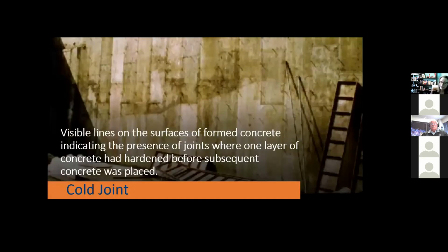But speaking of aesthetics, another thing that can happen is cold joints in concrete. You can get at times when placing more than one truck, joints that form due to one section of concrete hardening before the other is placed. Now, I don't think you can see my mouse, but you can see lines that are vertical, and those are the form work. Don't look at those.